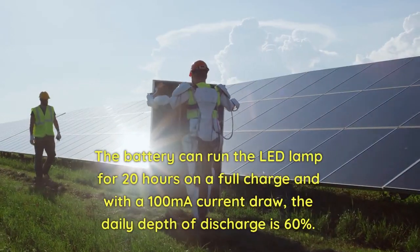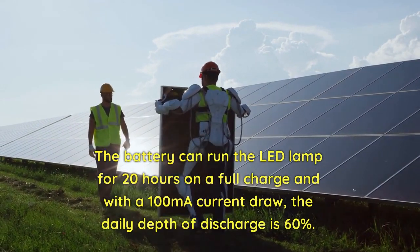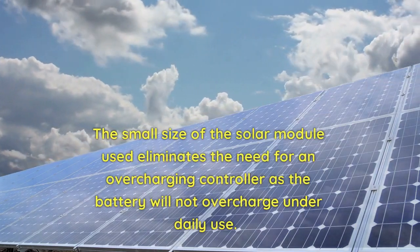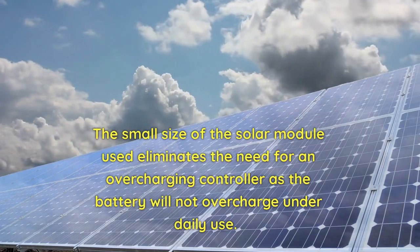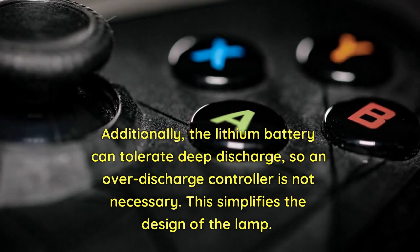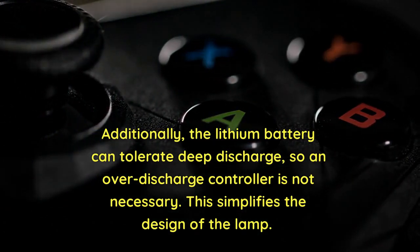The battery can run the LED lamp for 20 hours on a full charge, and with a 100 mA current draw, the daily depth of discharge is 60%. The small size of the solar module used eliminates the need for an overcharging controller, as the battery will not overcharge under daily use. Additionally, the lithium battery can tolerate deep discharge, so an over-discharge controller is not necessary. This simplifies the design of the lamp.